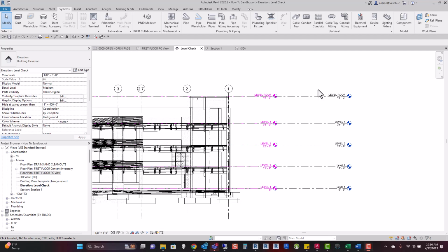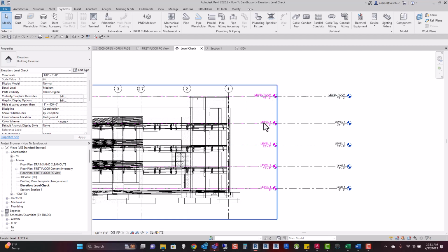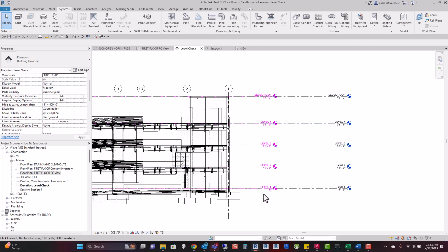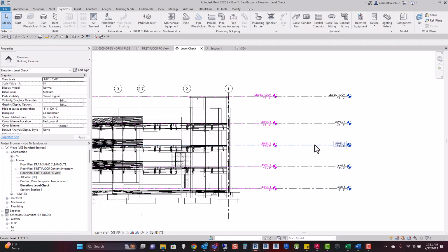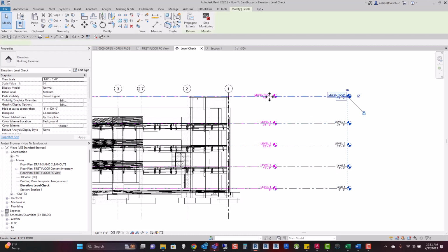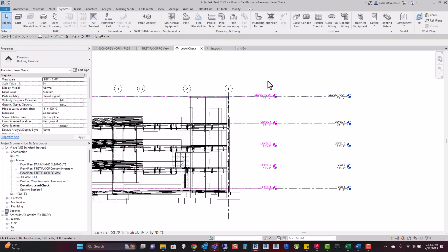Okay, today's Revit tip, we're going to talk about the Maximize 3D Extents tool. In this data set, I have pre-configured it so it's a little bit easier to identify. I've linked in an architectural model, and I've changed the levels in the architectural link to reflect as pink so we can differentiate between the levels on the link and our internally posted levels that are copy monitored back to this linked model.